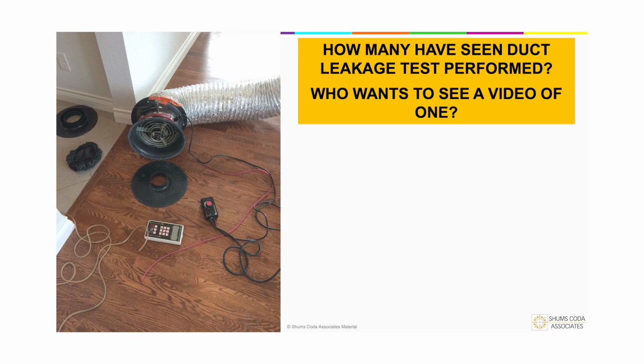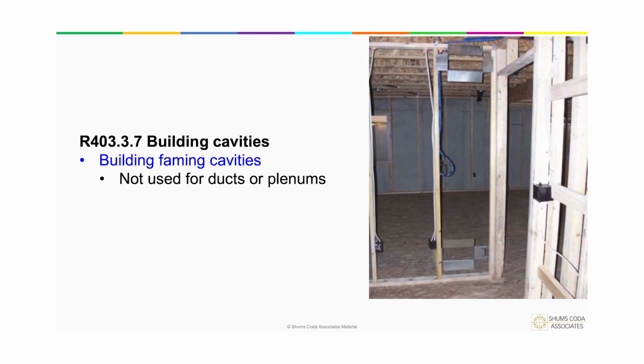All right. Oh, yes, I've done a lot of duct leakage testing. If you haven't done it and you're designing systems that are quite complicated, i.e. lots of ductwork, be afraid of the test. It's there. I do blower doors as well. We do tons of blower doors. I'm not as concerned with blower doors. I'm much more concerned with duct leakage. They are failing. The guys who have done this for years are failing.